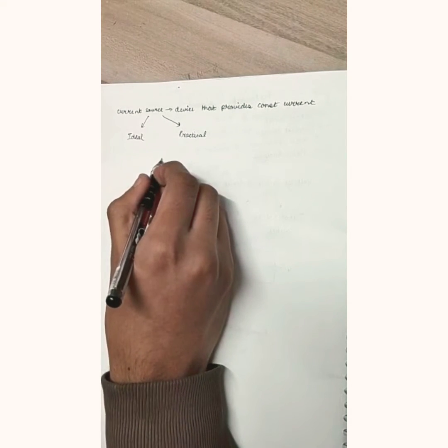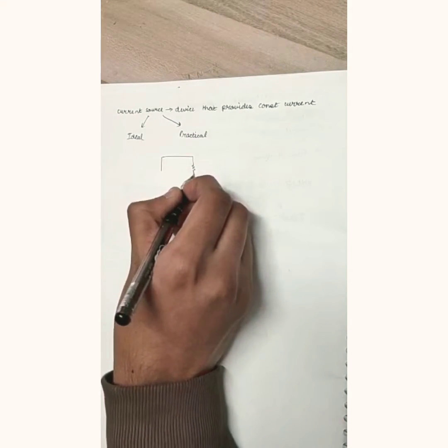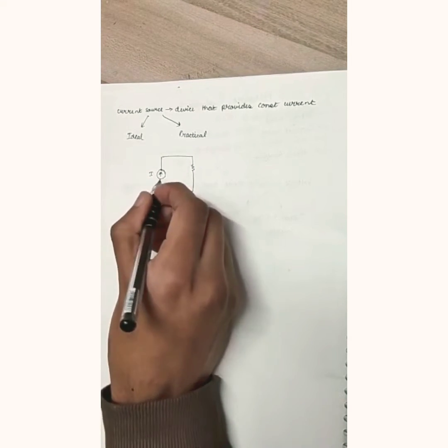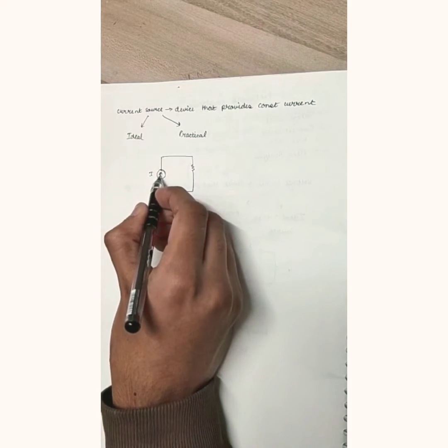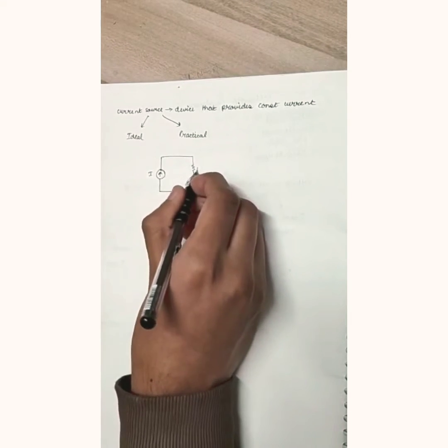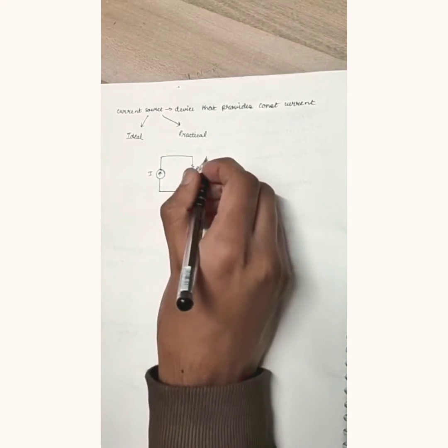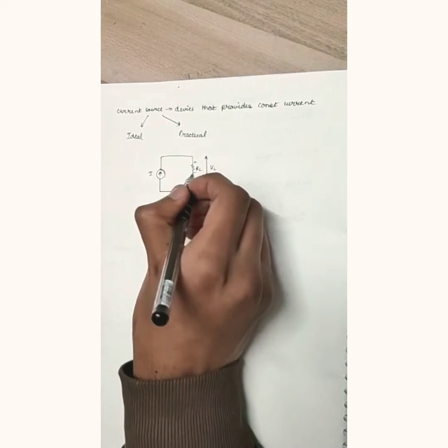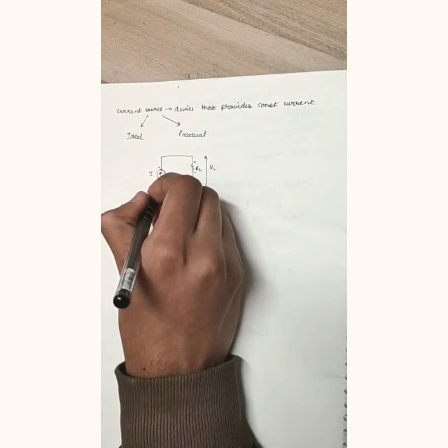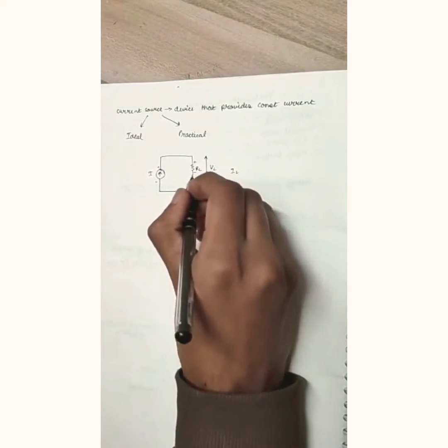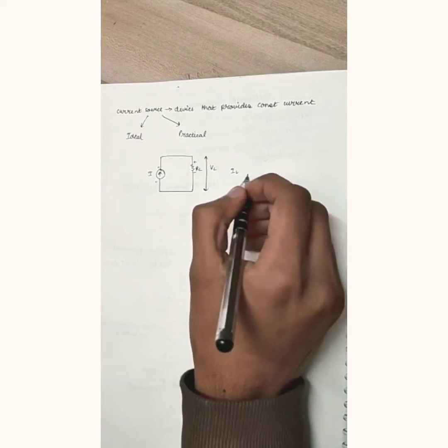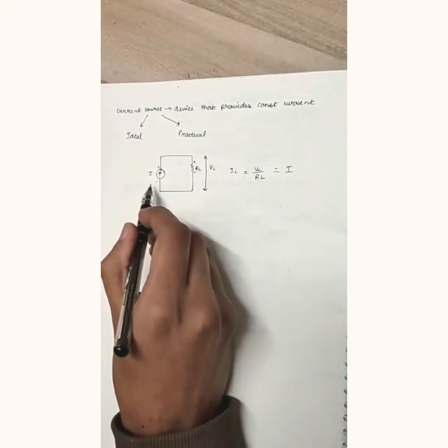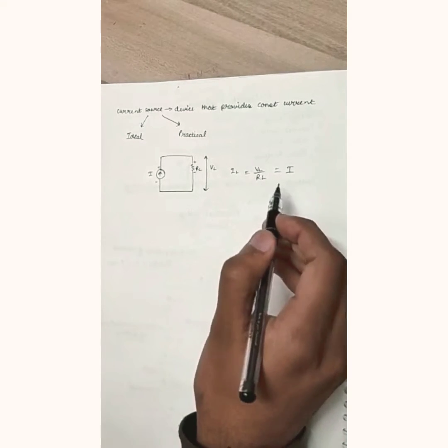So let us understand this with the help of a circuit diagram. Let's say there is a current source. We can show it by this particular symbol, which also shows the direction. Let's say a resistor RL is connected and the voltage across this RL is VL, and since it is coming towards this side, we will mark it as positive, negative. This will also be positive, negative. Now the IL, the current through this resistance, will be equal to VL divided by RL, which will be equal to the current being supplied by the current source. This is the ideal case.